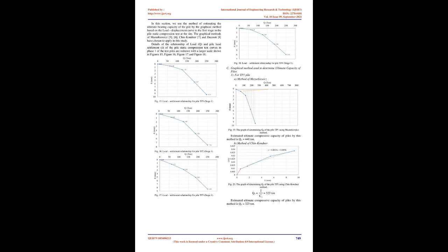The construction site is as shown in Figure 1. The soil profile at the site is reported to consist of clay and sand, and is presented in Figure 2. The water table varies from 3.3 m to 5.0 m below the ground surface. Test pile parameters: the pile selected in this study is a pre-stressed concrete spun pile PHC with D equals 600 mm, with the design load capacity QD equals 250 tons, the working load. Figure 6 shows the pre-stressed concrete spun pile PHC at the site.